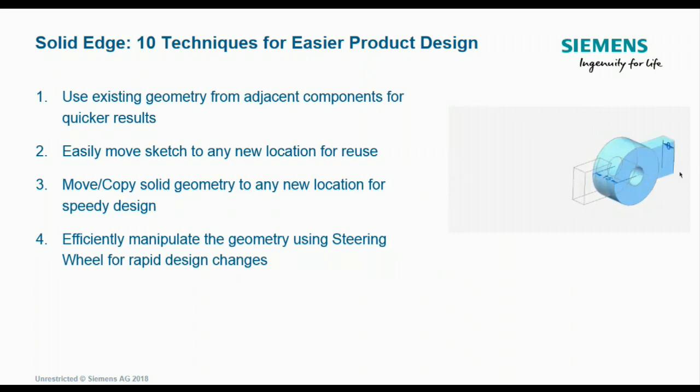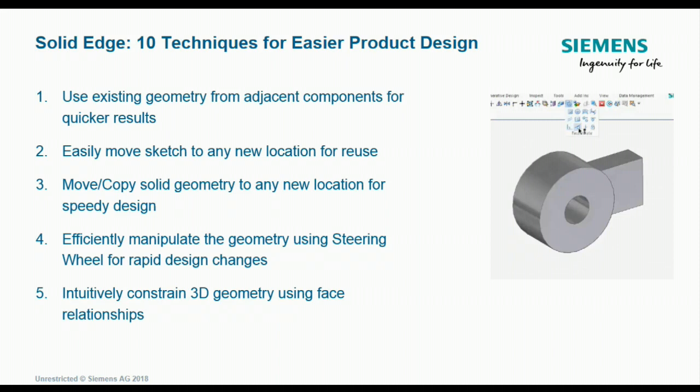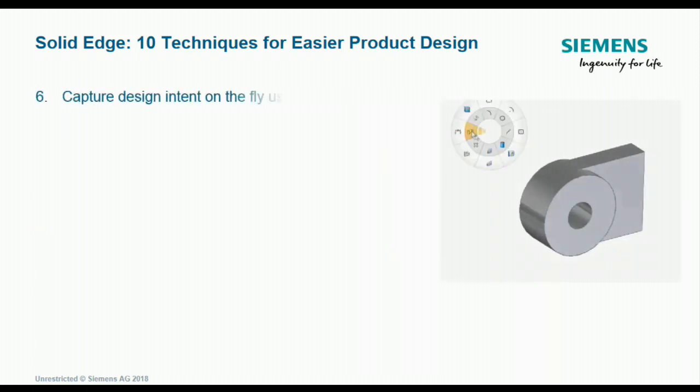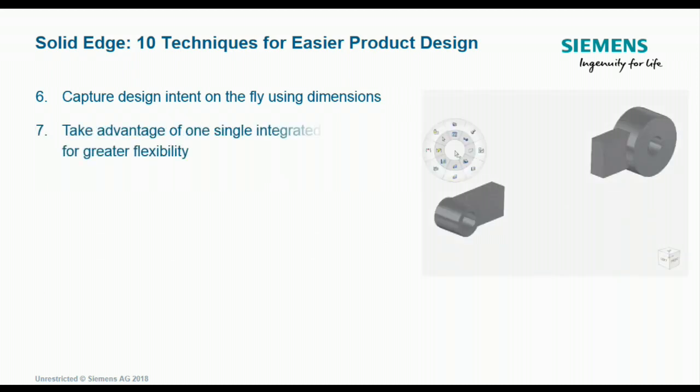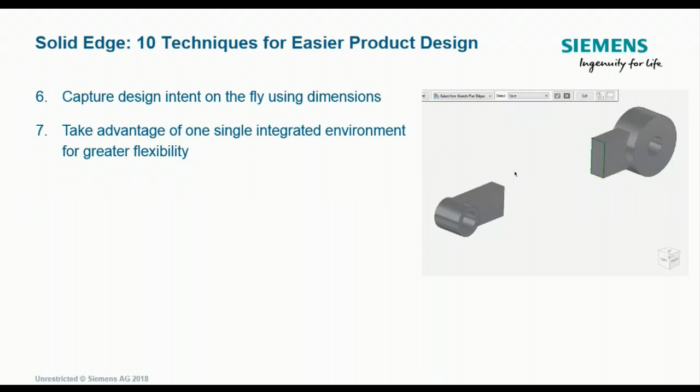It works the same way on imported geometry, providing unmatched capabilities for working with suppliers or customers' data from a different CAD package. Intuitively constrain 3D geometry using face relationships even on imported unparameterized bodies. Capture design intent on the fly using dimensions and bypassing the middleman sketch. Take advantage of one single integrated environment, combining direct model interaction with fully parametric features for greater flexibility.